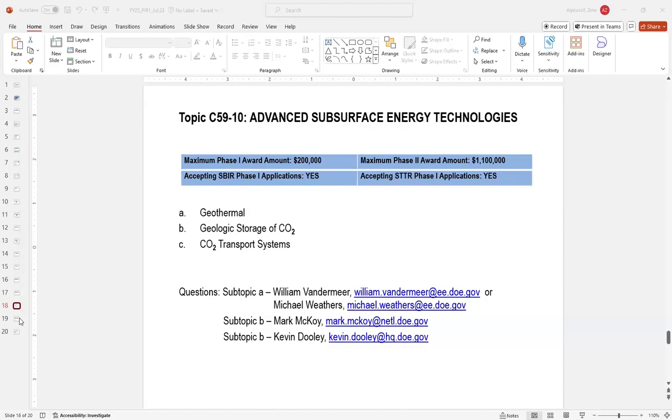In light of this, we're seeking digital tools and technologies that can model oxygen removal technologies and anything applicable to CCS. We're hoping to get the concentration down to 10 ppm moles or less, as we're seeing that's typical industry guidance. And we're seeking the digital tools to be able to model some of the process, understand some of the cost estimation related to that process and the conditioning equipment, and then be able to predict some of the CO2 stream compositions, especially the waste product stream and then the product stream.